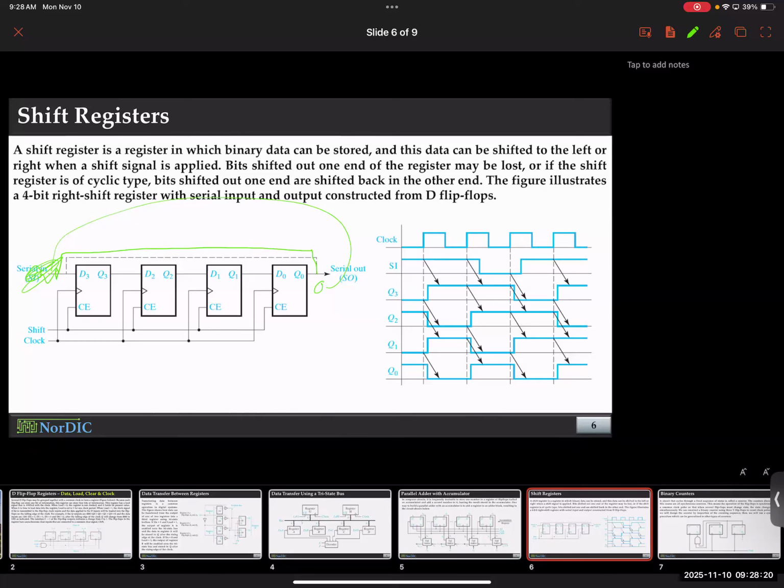That staircase you showed, a right shift? Yes, it is a right shift. So will the left shift be upward from the bottom? Yes. But by the way, that's a good question. Don't get confused as to the numbers. We are looking at D3, D2, D1, and D0, the way we have arranged this. But imagine if you start providing the input from the other side and just flip it over, it could be the left shift. So basically, there is no fundamental difference between left shift or right shift. You're shifting serially, that's all.